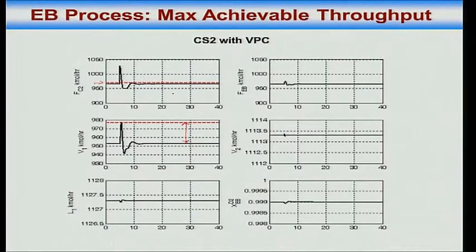This is only for one disturbance in the flow sensor ethylene. There are n number of disturbances operating at any given point in time. Not only the flow sensor, here the DEB recycle flow sensor, the total benzene flow sensor, the temperature sensor on the column, the heat loss in the column, day, night, etc. All these things are operating at the same time. So each one of these disturbances will add an extra back off. So what seems like okay only 0.5% loss may actually turn out to be 1 or 2% when you take the effect of everything together. 1 or 2% throughput loss because of back off in the boil up, integrated over a year of production, will translate to millions of dollars, right?